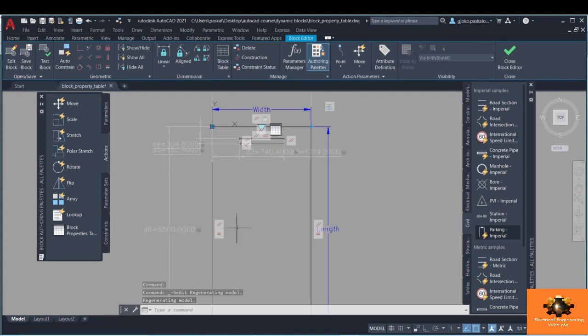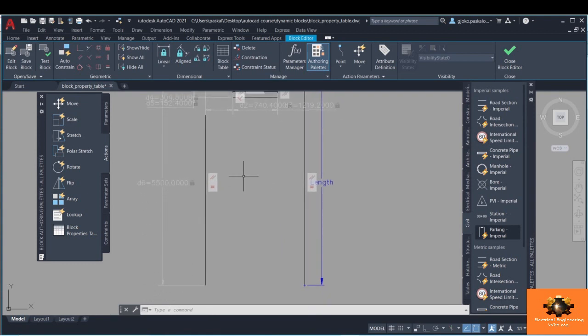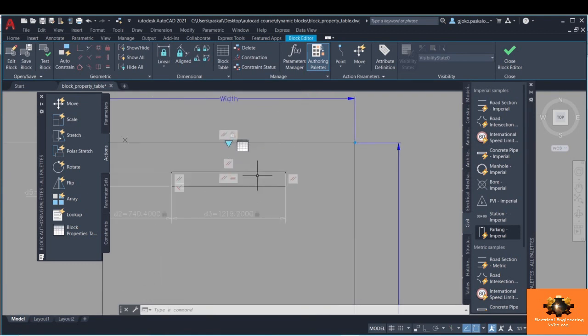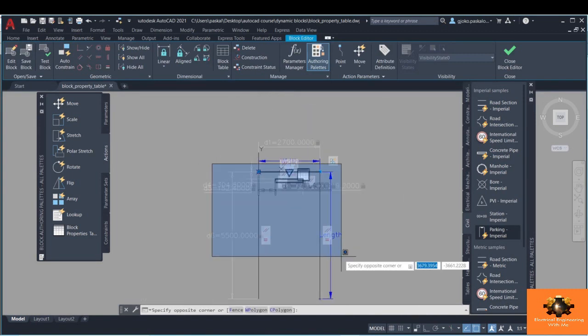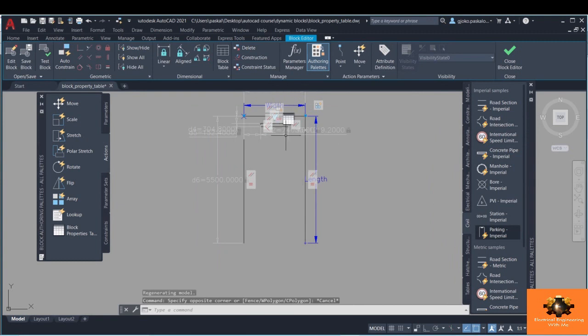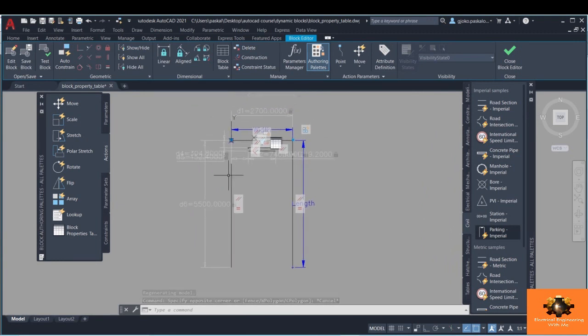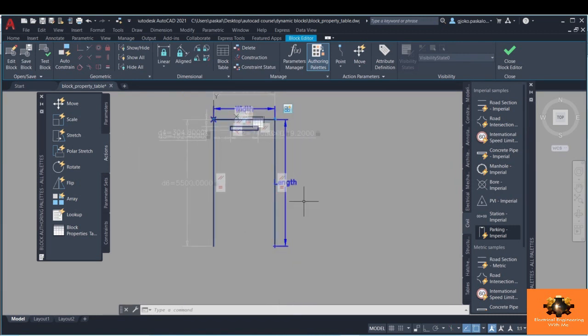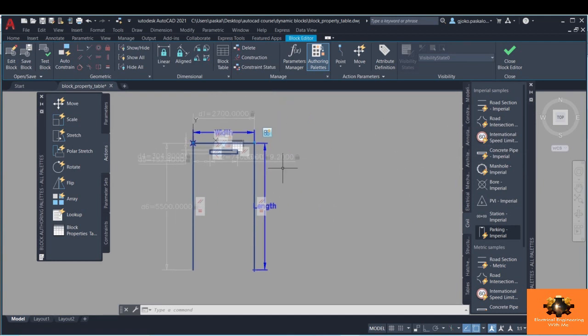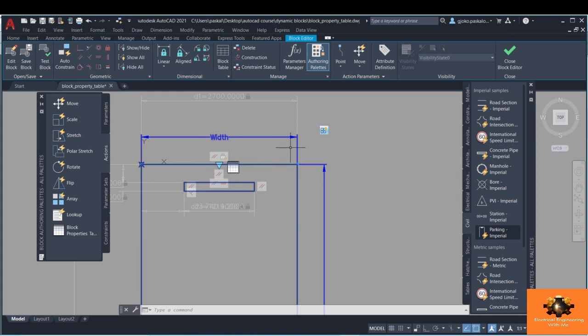As you can see, basically we have the same case. Geometric constraints are assigned, so we have all the lines connected to each other and maintain the same form. Dimensional constraints are assigned to maintain the dimensions of the block, and actually these dimensions are manually set, so they do not depend on anything, and the whole action is assigned with a basic array action. So all the constraints, all the drawings are connected with an array action that allows us to multiply the parkings in the direction we need.